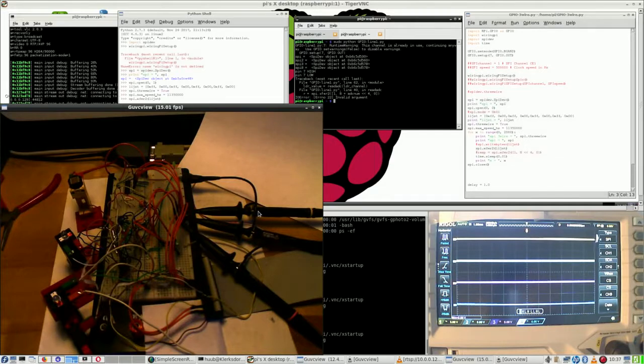Then there is a problem with spidev. spidev seems to have a problem which directly relates to a possibility or a non-possibility with the GPIO. It seems to block on a very low level.